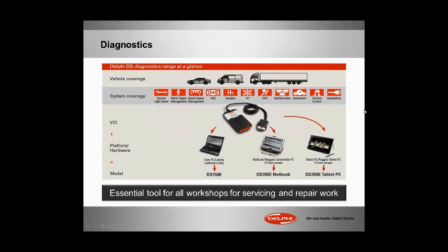Okay, I'd just like to start with an overview of the Delphi Diagnostics product. You'll see in the center here the Delphi VCI, the vehicle communication interface, which connects to the vehicle, and then we use Bluetooth to communicate to either a DS150 that we call, and that would be using the customer's own laptop, or we have a DS350 solution with a netbook PC, and also a solution using a larger tablet PC for the larger screen size and higher processing power.